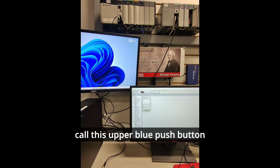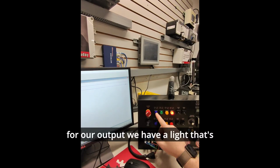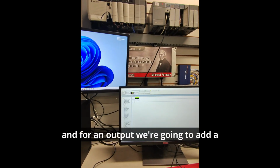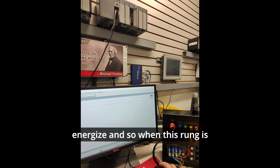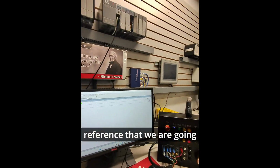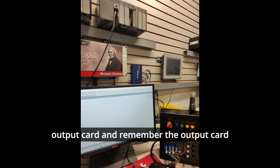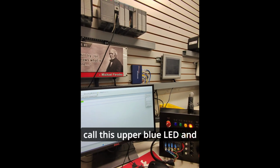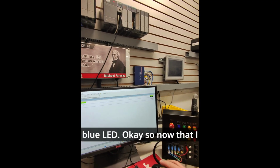And we'll call this upper blue push button. For our output, we have a light that's going to be referenced by the output slot, which is slot 2. And for an output, we're going to add an OTE, which is an output to energize. And so when this rung is true, that light will turn on. So to reference that, we are going to use channel 0 of the output card. And remember, the output card is in slot 2. So we'll call this upper blue LED. And for the symbol, we'll just do U_blue LED.